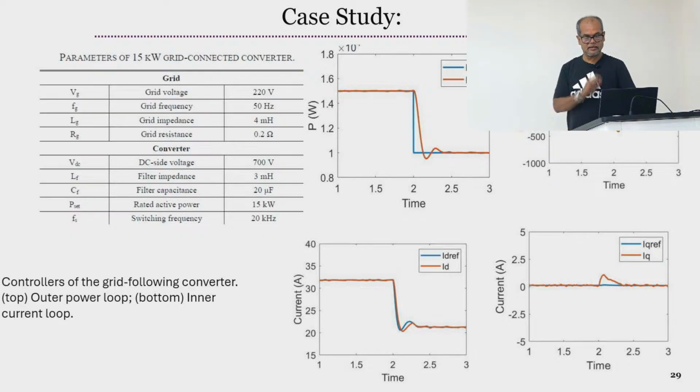That is always the test you should perform after designing the control. And you see that not only PQ, but also the DQ current reference is followed, as we are normally giving 0 reactive power. That is why it produces 0, but what I am trying to say is that it is following the reference.